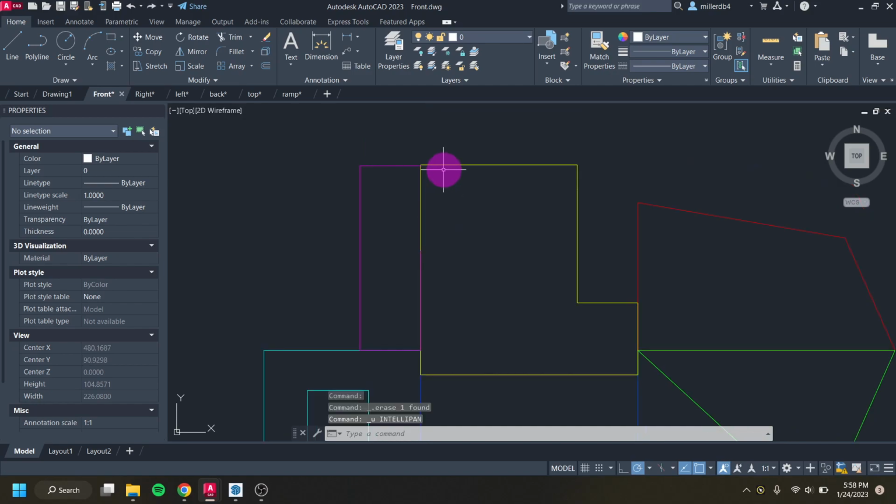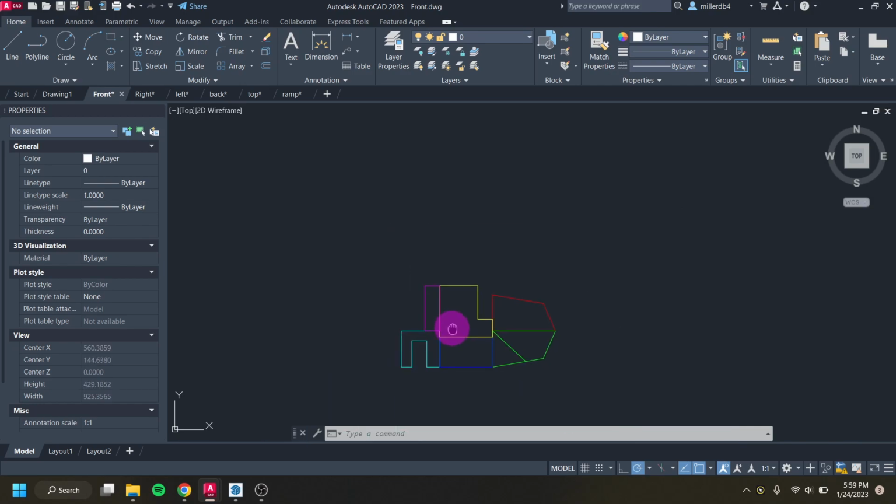So if I undo, the laser is going to cut that magenta, but then it's also going to go back a second time and cut out that yellow edge because there's two edges sitting there. With a lot of materials, that's going to pose a huge problem, especially things like corrugated cardboard and foam board, because if the laser's already gone through there, and then it focuses on that same area again, it could start to burn and smolder. And since we're watching the laser, it's not going to cause a huge commotion where the building burns down, but it is going to ruin our project. And that's also not an end result that we would like.